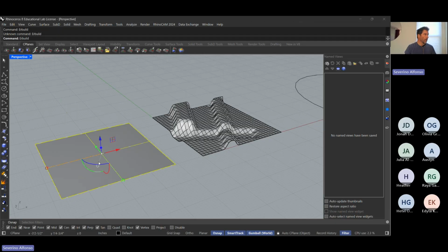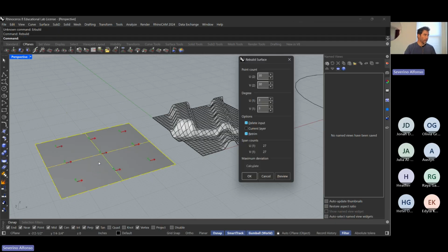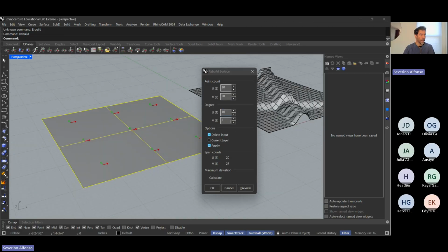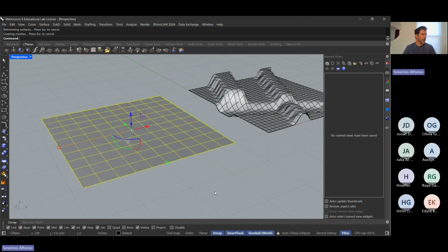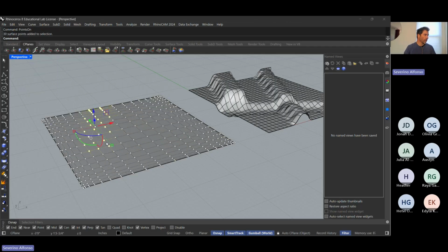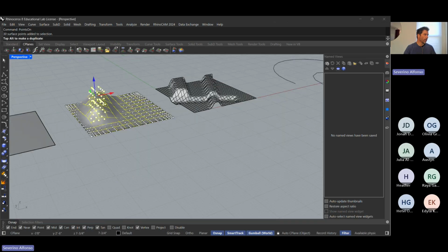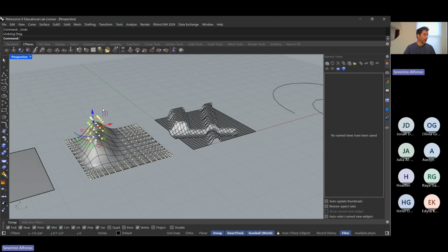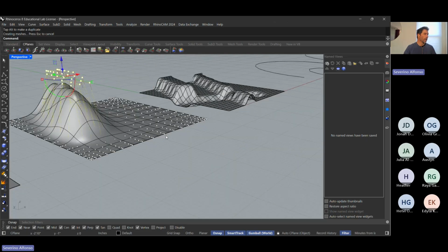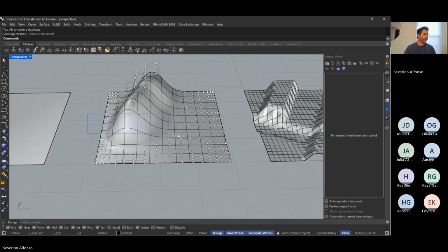There are many possibilities of rebuilding. As you can imagine, you can change the number of points, but also the degree. I could set this to 10, and let's say 20, just number of points, say okay, and I turn on the control points. There are fewer points, but look how, no matter how much I move this, the surface is quite relaxed in relation to the points, so it creates a softer curvature degree.